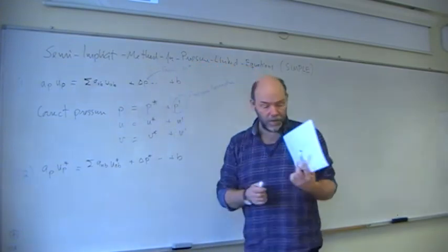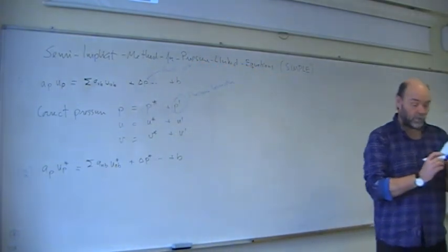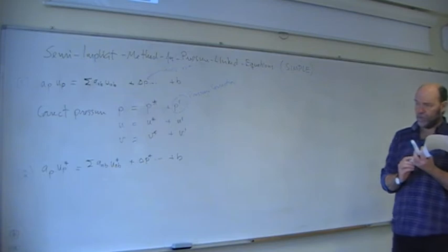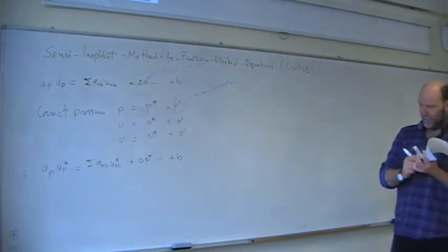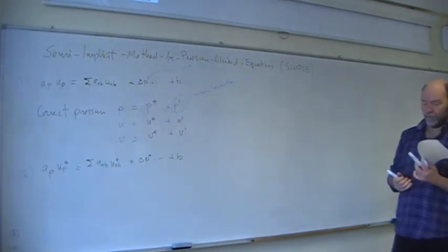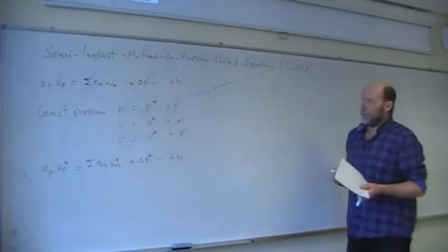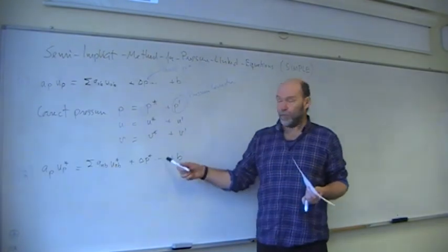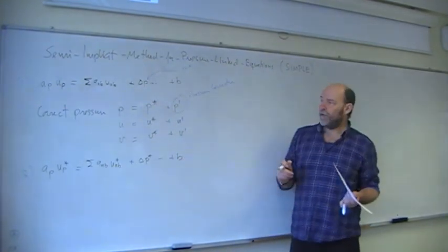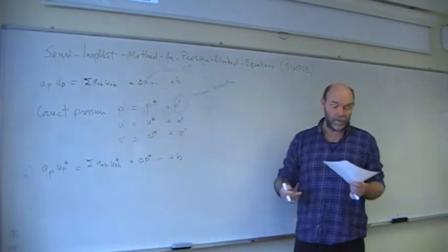So you might say equation number 1, that's the one we would like to solve, but we can't. Equation number 2, that's the one we can solve when we use something wrong, the wrong pressure. And typically the pressure from the previous iteration, or if it's a transient code, the pressure from the previous time step.